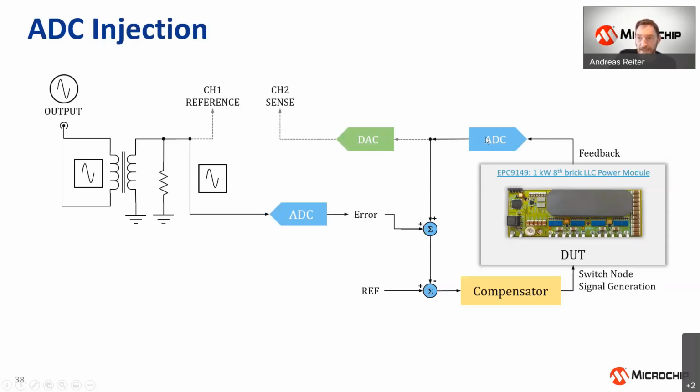Again, there's sampling time and conversion time until we can read the value from the register and push it over into the DAC, so that the DAC adjusts the output, which is provided to the sense input of the Bode 100. We can shortcut this a little bit by utilizing things like direct memory access, so that every time a value gets updated, it's pushed over to the DAC register automatically in the background, so that we don't have to use software to do this.